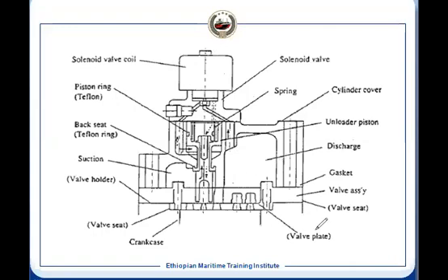And when you start the compressor, what will happen? All the solenoid valves will be de-energized. So when you start the compressor, it has to be in unloaded condition, so all the suction plate valves will be in open position. After that, when it comes to the normal RPM and the amps are normal, it will be loaded. Initially for starting, all will be in unloaded condition. After that, depending on the temperature sensor, the set value and the measured value, accordingly it will be loaded automatically.